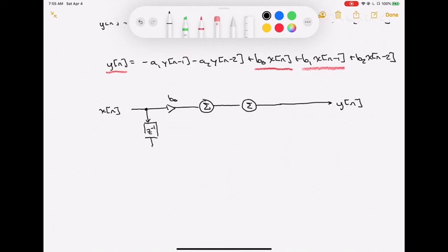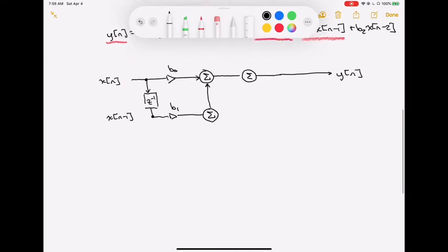So we're going to come out of there, and what do we get? We get that x of n minus 1, the input delayed by 1, or you could think of it as the past input value. That's the memory part. That's going to go forward, and it's going to get weighted by that factor b1, and that's also going to get summed in to help us make that output. So I'm going to put a summing block in there as well. Go ahead and give myself some paths here, and I'm just going to sum that in. These are all the feedforward terms. If you remember those b terms, the ones that end up multiplying our input terms, are also the things that form the system zeros. So we are working right now at an implementation that is helping us get the zeros of our system.